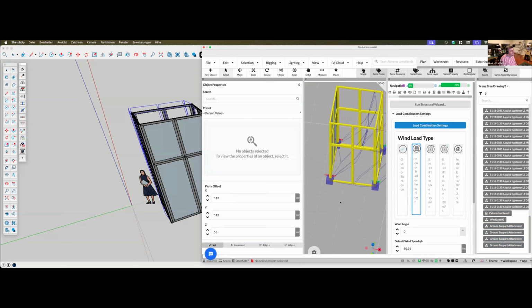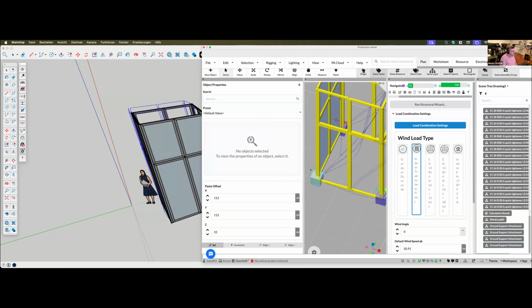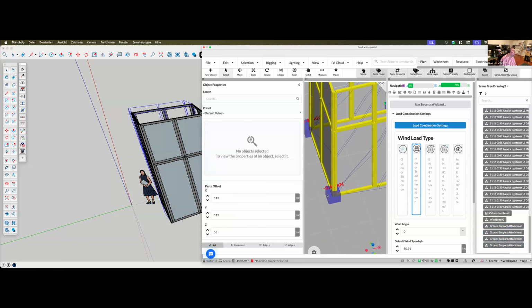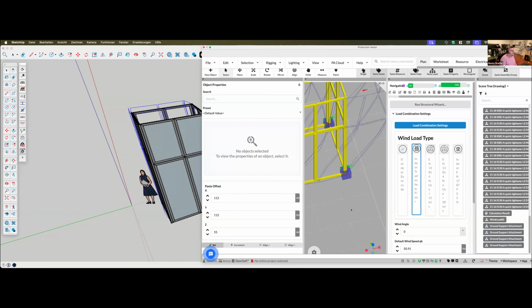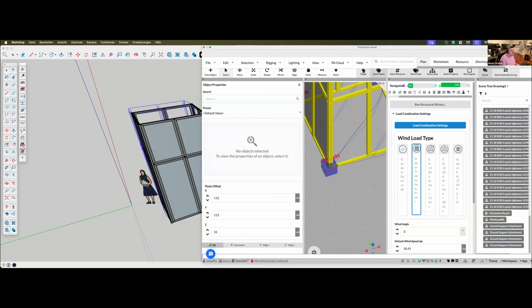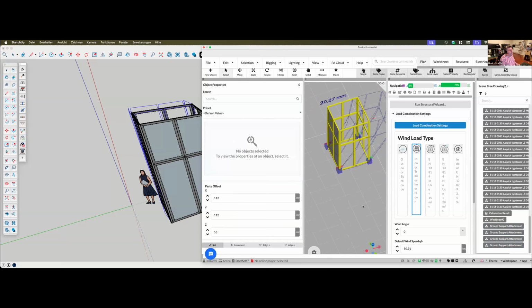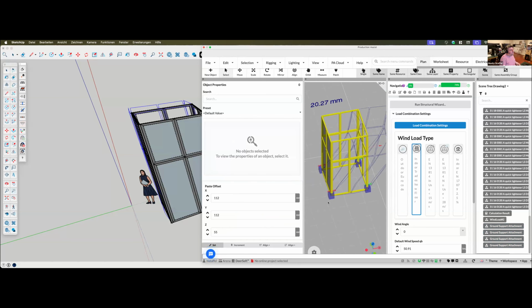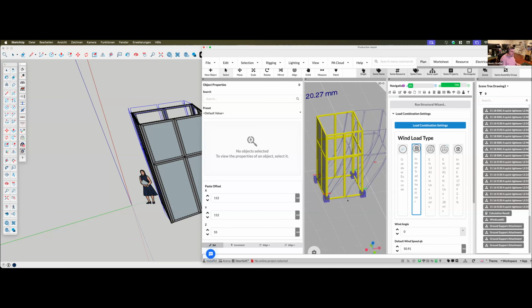So I see that basically on the left side, the reaction force is 0.4 kilonewton, and on the right side, the reaction force is 1.7. So this currently means that it's tipping, because it actually needs something that is holding it down. In trade shows, you normally don't screw to the bottom. It's possible. So if you would screw it to the bottom, you would need to make sure that this connection is in here. But in normal applications, you now would need to calculate how much ballast you need.